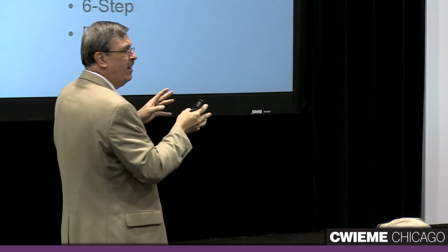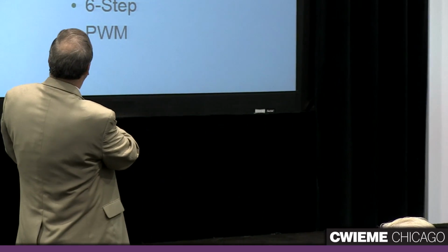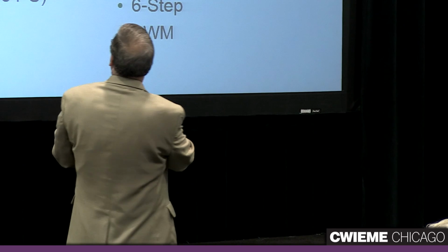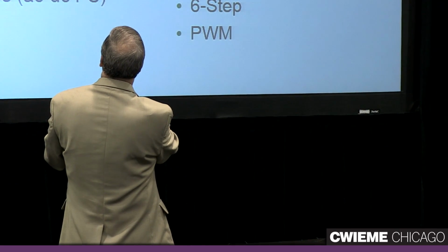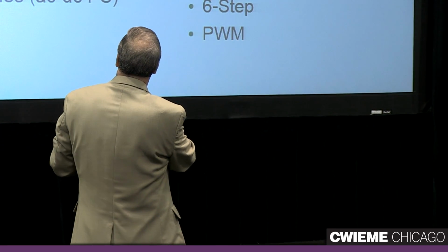It's ugly. I'll show you what it looks like. But it's not totally ugly. It's kind of interesting, but it's not a sine wave. DC drives, AC drives, for single-phase, fluorescent lights with the ballast, incandescent lights with light dimmers, computers, monitors, TVs, compact fluorescent tubes. All of these are nonlinear loads, and they produce current waveforms that do not look like sine waves. Therefore, they produce harmonics. So when we talk about harmonics, there's really three parts to these things.